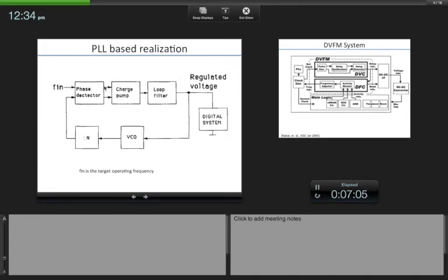The question is, as this loop is working, it's trying to adjust the supply voltage. So if you go and adjust the voltage of the charge pump as well as the op-amp with the same supply voltage which you are adjusting, it might actually not work properly. So there could be a lot of problems in trying to get that to work. And so you don't want to get into that kind of complication, mainly because these circuits are supposed to be very low power consumption circuits. You should not be consuming too much power. So there's no point in complicating your life and trying to reduce the power of these any more.